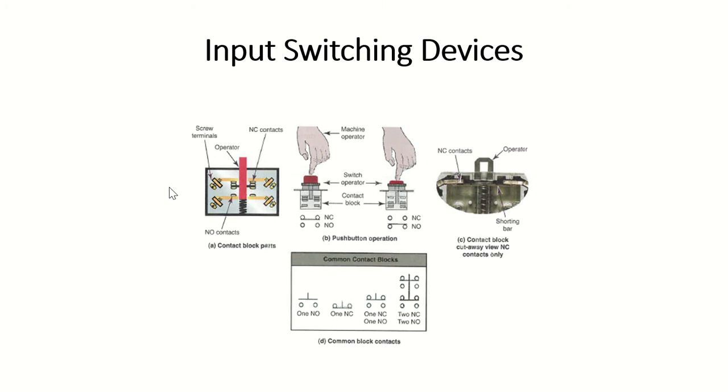Very, very high resistance, because it's the resistance of the air in between those sets of contacts. Whereas my normally closed set of contacts, again not pressing the button, I would read very, very low resistance, like 0.2 or 0.3 ohms, a very good conductive path. And those are referred to, again, as the out of the box or not activated state.